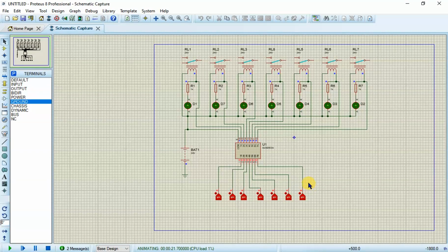So that means when we have our PCB and we have here the inputs as 5 volt signal or TTL logic, it is going to help us control our 24 volts relay output. And with the relay output, we can control anything. We can control a motor, an alarm, lights, anything you wish to control. Any power, DC or AC, you can control using this IC, which is very cheap. That's what you should know. Using that IC, we control high power using the signals.